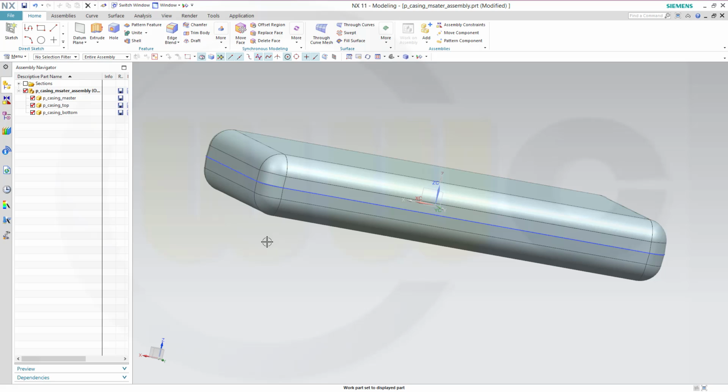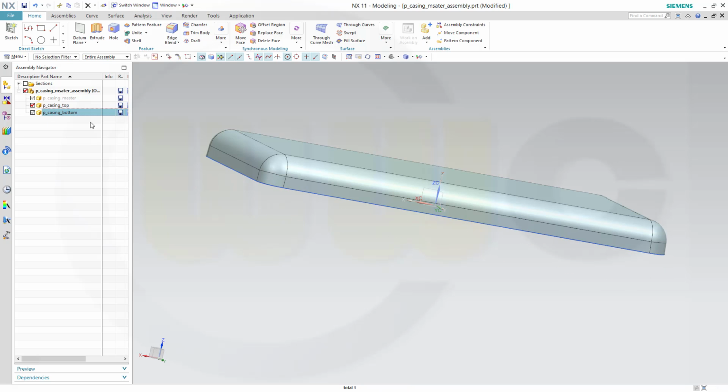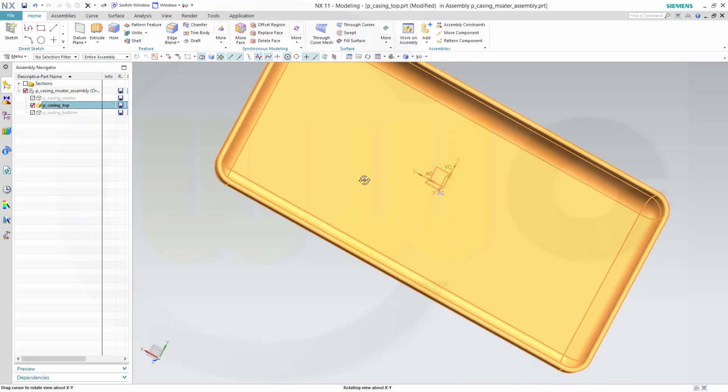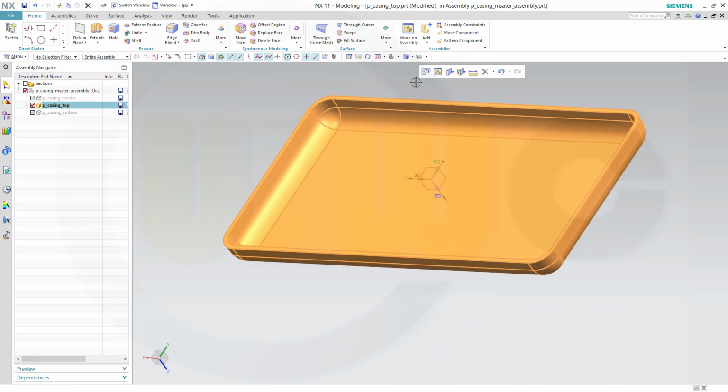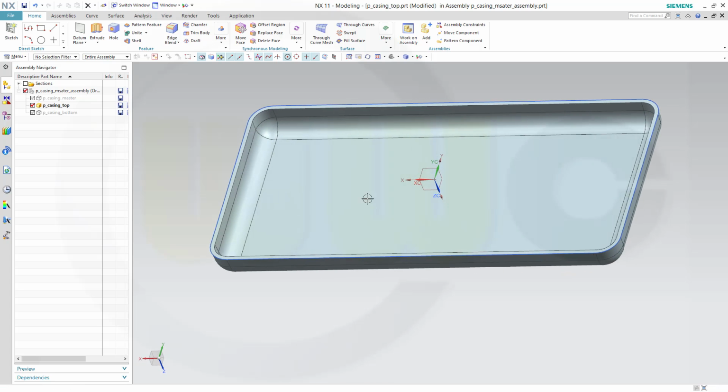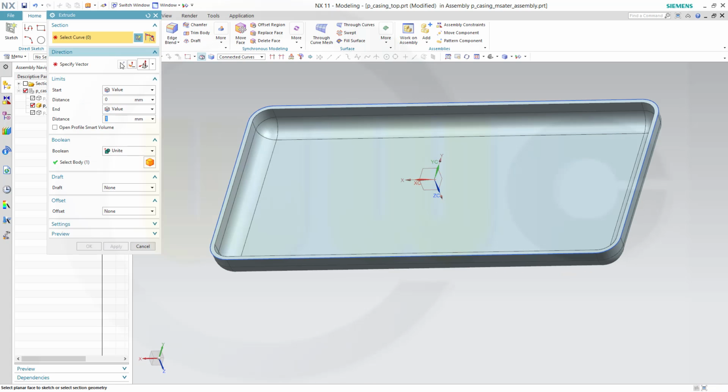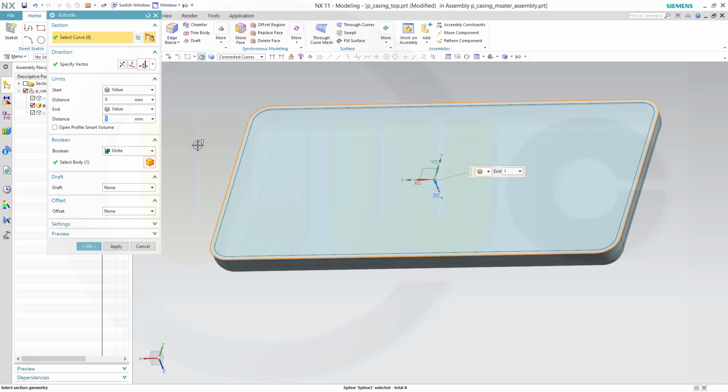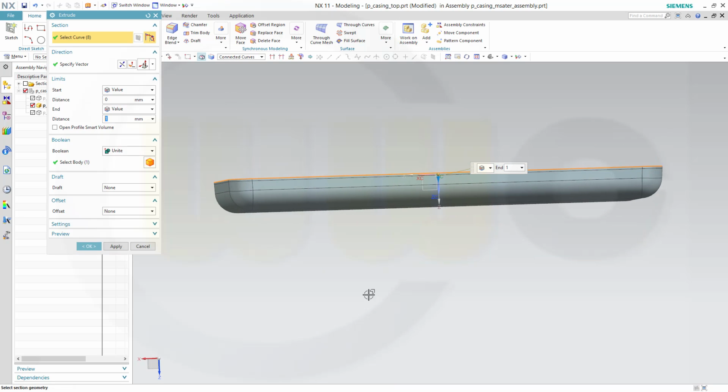So now let's add the upper and lower lip. Therefore I would go to my casing top and use that sketch and make an extrude. You could do it with a sweep or an extrude along a guide, of course. So that would be the curve. Now it should go 1 mm in that direction, yes. I want to subtract it,